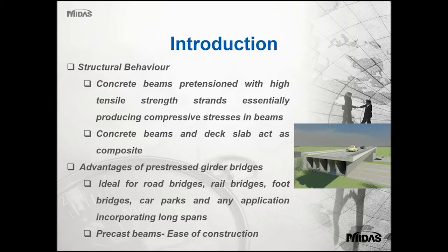Advantages of pre-stressed girder bridges: well, they can be used for any type of road bridges, rail bridges, footbridges, car parks, so any type of long span applications. We can use this type of pre-stressed concrete beams. The second advantage is ease of construction, because the beams are precast, so it is easy to construct the bridge.